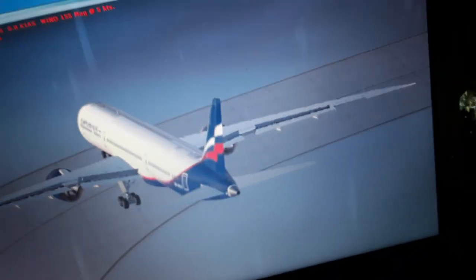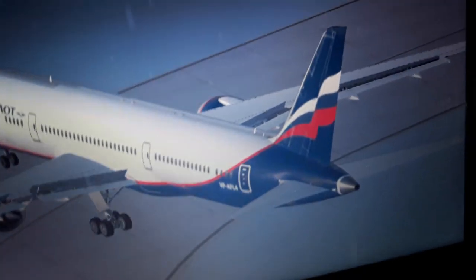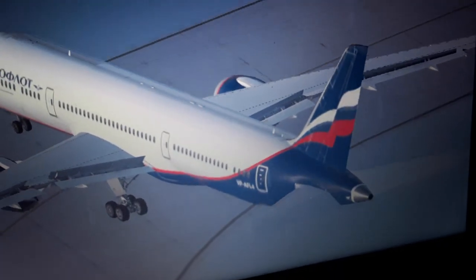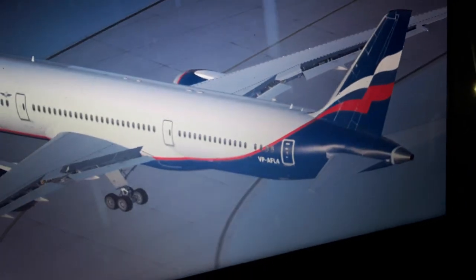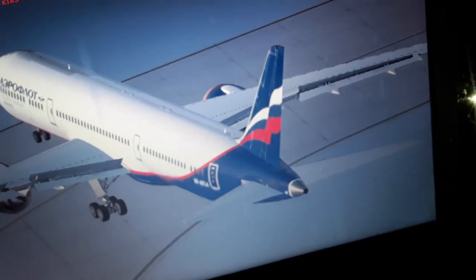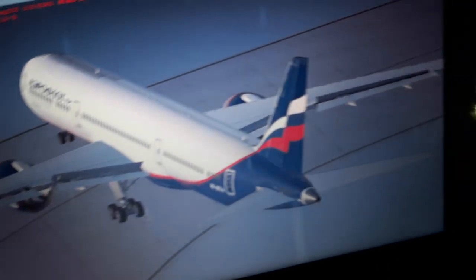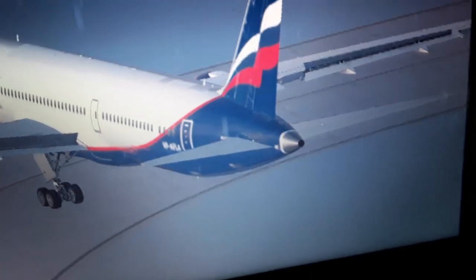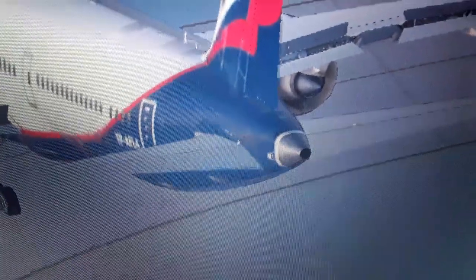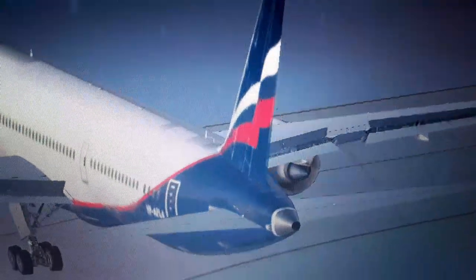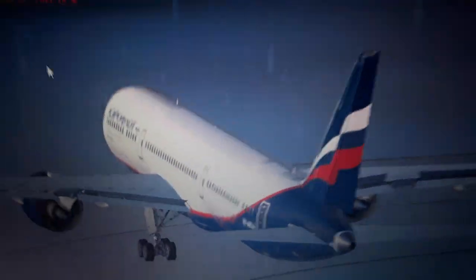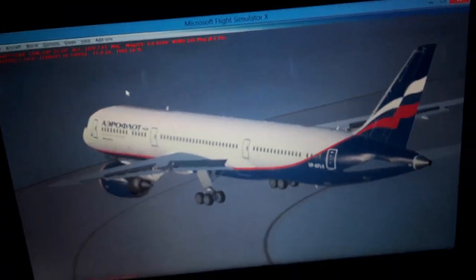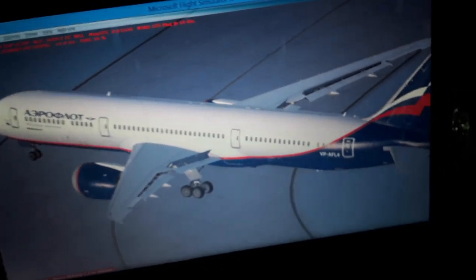We're gonna explain a little bit of aerodynamics and flight theory. So you have the elevator for climb and descent, and also you can trim it. You can trim the other surfaces like the rudder, also the ailerons and the spoilers in this aircraft. So mainly it's the horizontal tail trim, as you can see. So we're gonna have the explanation for that before flying the aircraft.